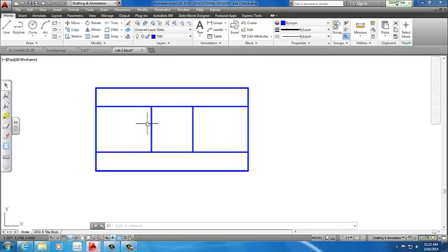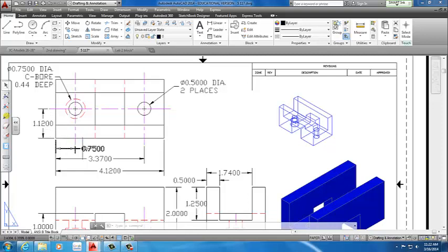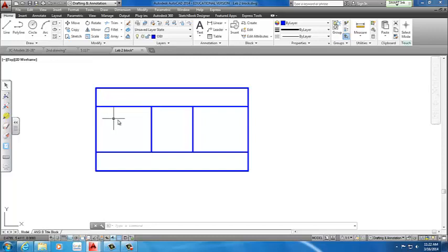So you go to trim, you select the entire object. Alright, I have this top view. What I want to do more is create these circles. I have to specify a distance of 0.75 to the center of the circle. Then I can select offset, this line you want to trim, which is going to be the top circle. Actually, we're trimming both of them a little, because both of them are 7.75 from the right edge.